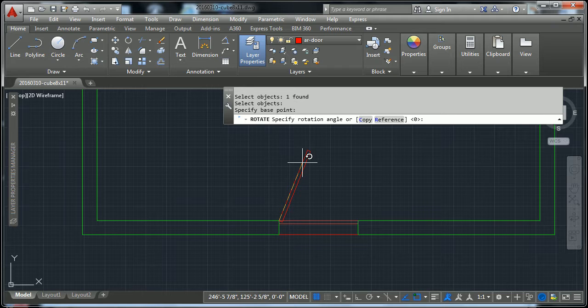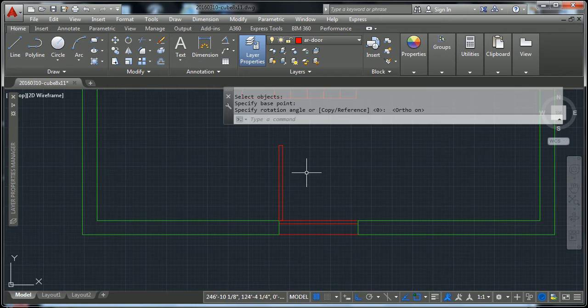If you had the F8 on, which is the ortho, it will go into a 90 degree lock, right? Or you could type in 90 degrees, because it measures counterclockwise. It might be just easy to go ahead and turn on the ortho and open it 90 degrees. The lines that are here right now, I could select and delete, and the door shows up. Okay.